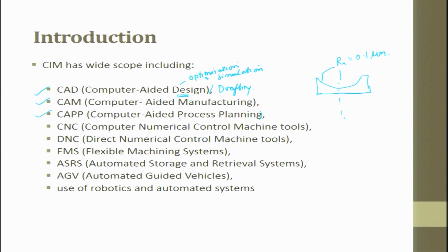For this to be established, you should have a standard database. So that standard database should look at features. First it has to recognize features, and then each feature has to be linked to the process, and it should have the data. And by and large, people try to use a decision table to store the data. Next one is computer numerically controlled machine tools. CNC is also part of SIMS. When there is a single server and you have more CNC machines attached.